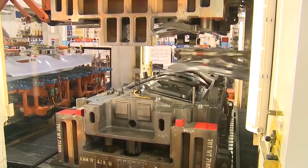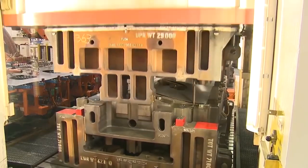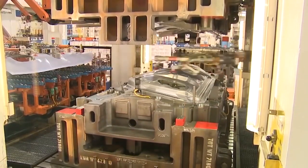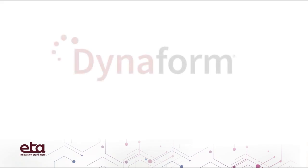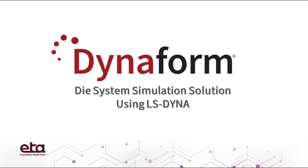Modern sheet metal stamping involves the processing of advanced sheet metal materials into complex shapes. The application of these materials results in sheet metal stamping defects that include cracks, wrinkles and springback. Dynaform offers complete die system simulation solutions to tackle sheet metal stamping defects by marrying a streamlined simulation process with the advanced nonlinear finite element solver LS-DYNA.